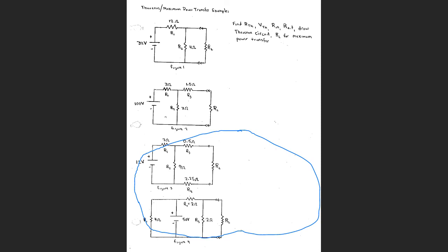So even though that resistor is hanging there, when you put the voltmeter across it, since there's no current going through it, because the voltmeter doesn't draw current, there's no current going through the voltmeter. So by putting this here, you're not closing that path off. There's no current flowing through R3, so it's like R3 is not there. It's just like a piece of wire. You could put the voltmeter here, and you can move it over there. It'll have the same exact voltage because it's like R3 is not there. It's not dropping any voltage. So whatever the voltage is across R2, that's going to be my voltage across A and B. You can ignore R3 if it's just hanging there.